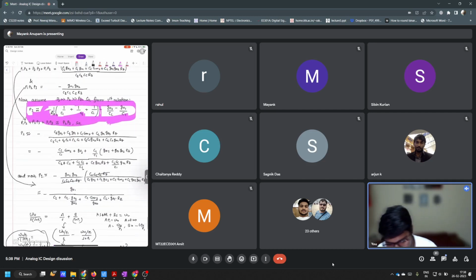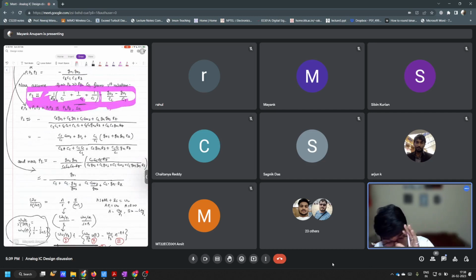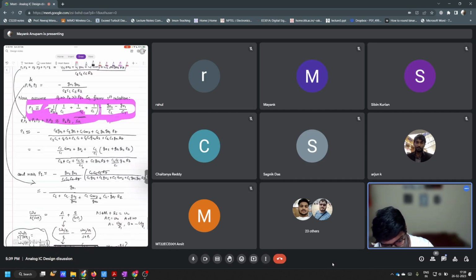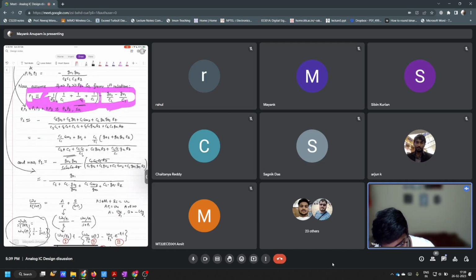So these are the approximate pole locations. You can see P3 is because of this RZ, and this will be at very high frequencies. Now the pole location P2 was actually what? This is a complicated looking expression here, pole P2, but you can see that it also has the same kind of behavior. You see, there is this gm2 times CC divided by C1 expression here, and here also you have this CL into CC by C1.